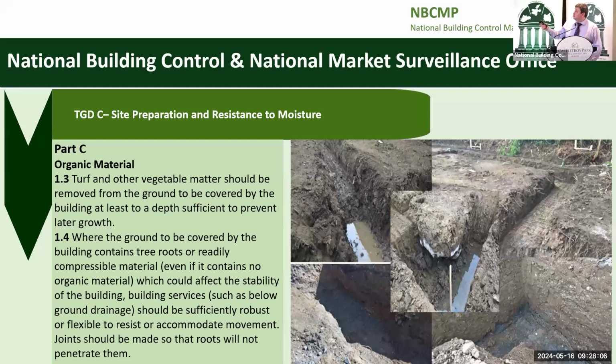Like you can see, these are photographs taken on site visits, and you can see the depth of the foundations is increasing, and the vegetation. Someone has to, they might use it as temporary, but then you have to make sure that all that vegetation is dug out and taken off site, and that the water is out of the foundation before you pour it, because there is enough water in concrete, as Tom from Roadstone will talk about in his presentation. You don't need to add any more water on the site when you've designed the mix.